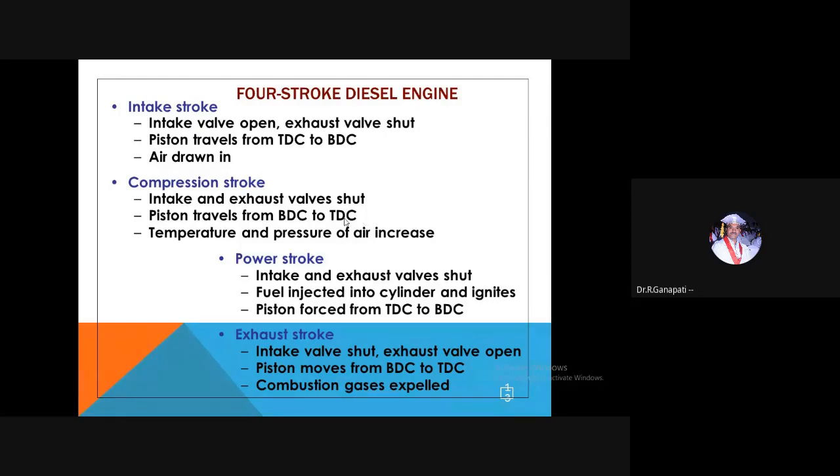In the intake or suction stroke, especially for the compression ignition engine, when the piston travels from the TDC to the BDC, the inlet valve is open. At that time, the exhaust valve is in the closed position. Only fresh air is drawn into the engine cylinder by the pressure difference.